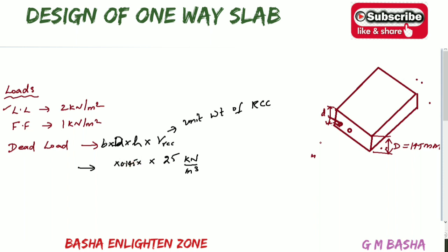And again, what about this B and H? Here we are calculating the slab for 1 meter. So already we know that D value. In terms of breadth wise it will be 1 meter, in terms of length wise it will be 1 meter, like this, 1 meter by 1 meter. So therefore I am considering 1 meter, and here also 1 meter. Then if you simplify this directly you will get 0.145 into 25, 1 into 1, in terms of meters. Whatever value you calculate, you will get in terms of kilonewton. That value will be 3.625